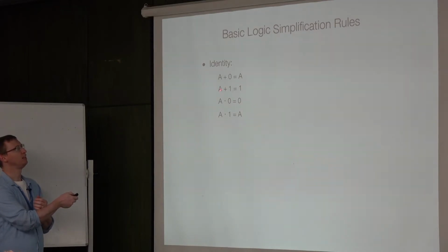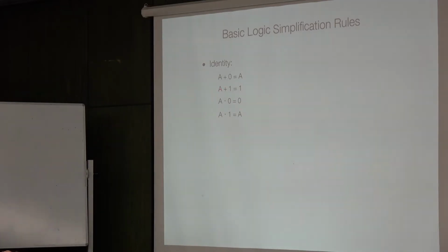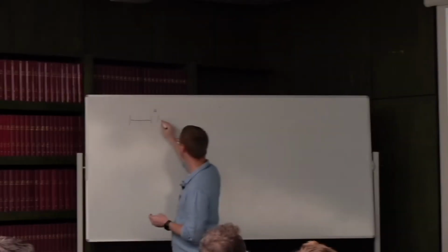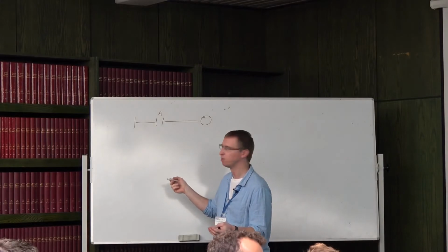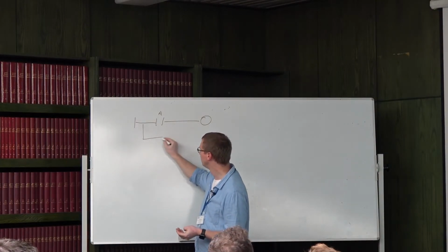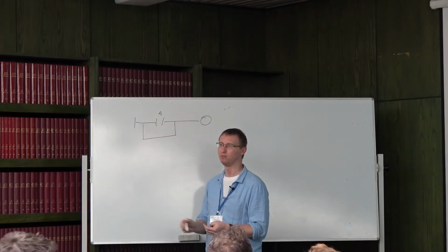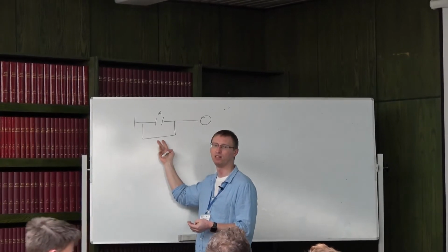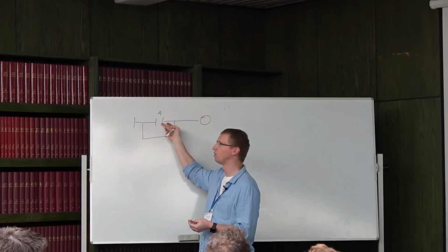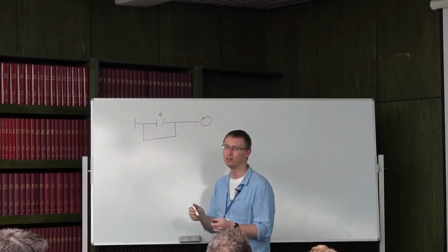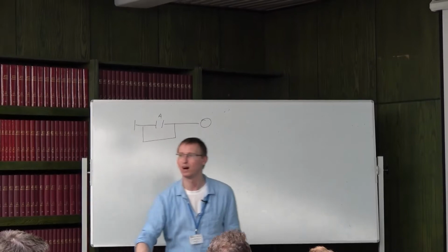What does it mean, A plus 1? Well, how would it look like in the ladder diagram? Well, plus means a parallel route, right? So the first parallel branch has this contact on that. And remember, here we are energizing, say, a lamp. But there is a second parallel branch with just a true value on that. That means there is no switch here which would prohibit the current to flow. This obviously just means that the current will not care about A and it will just energize the coil, right? So A plus 1 is just equal to 1.